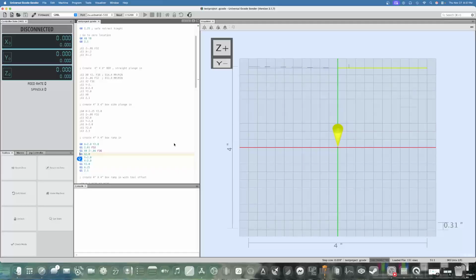Then it's pretty much the same as the others. It goes +2. We go Y from +2 to -2, which is 4 inches. We take X, which was +2, and now we're telling it to go to -2, which is again 4-inch travel. And then Y, that was -2 up to +2. Now X, we're going to 5. And the reason was that this got finished going to -60 on the Z at 0.